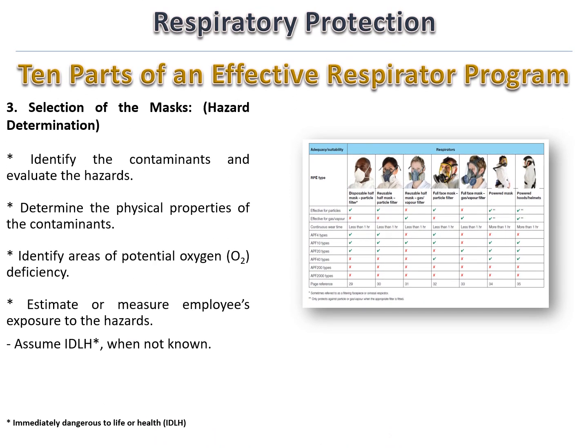Three. Selection of the masks, hazard determination. Identify the contaminants and evaluate the hazards. Determine the physical properties of the contaminants. Identify areas of potential oxygen, O2, deficiency. Estimate or measure employees' exposure to the hazards. Assume IDLH when not known.